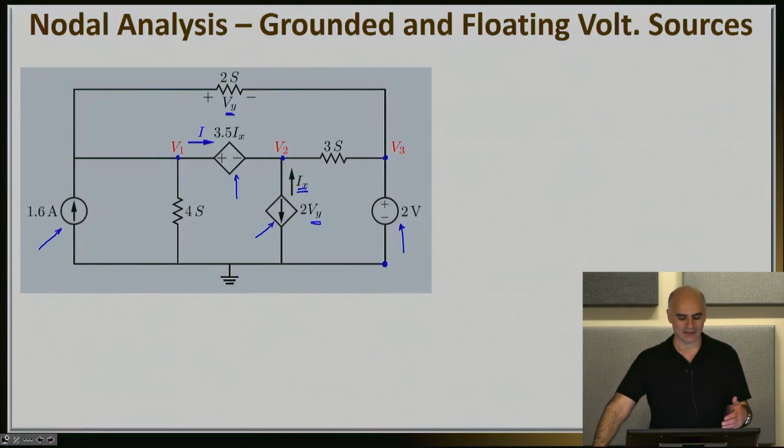I should actually clarify that in this particular circuit, I am basically giving you the conductances instead of resistances in the elements that you see here. All right, so we're going to proceed with all the steps that we know already for nodal analysis until we come to a point where we have to think about perhaps something we haven't seen before.